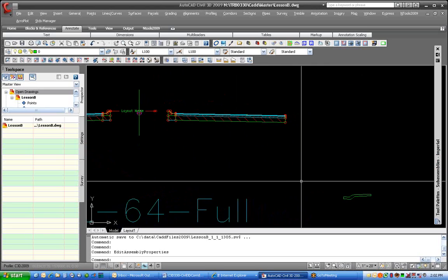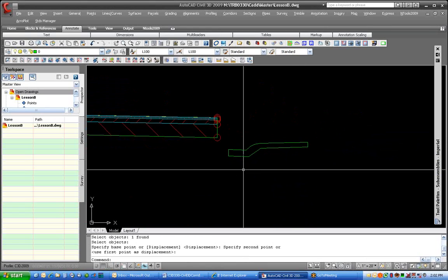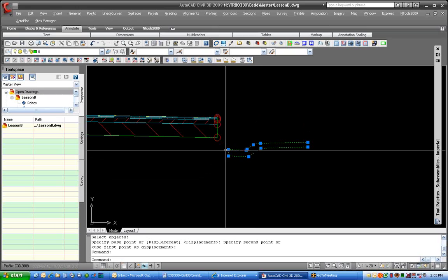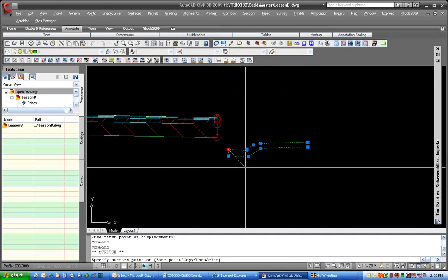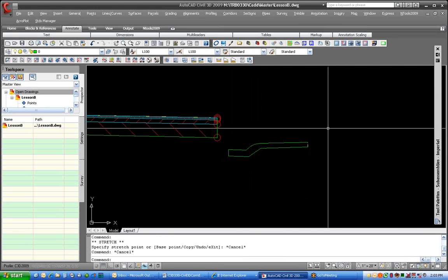Let's finish this off now by putting in our curb. Let me move this up to where we can see it here. I've already drawn the polyline just so you guys don't have to watch me draw a polyline. Let me pick on that. It is a closed polyline, and the only thing I'm going to suggest is that you start drawing it at the point you want to connect it. So I've started it at that vertex as the beginning point. I drew it going in a clockwise direction just out of old Land Desktop habits and then closed it back on itself. That start point will become the connection point when I build a subassembly out of that.